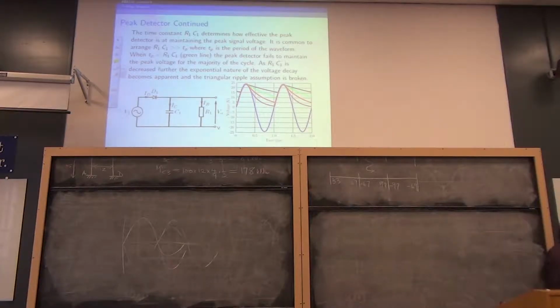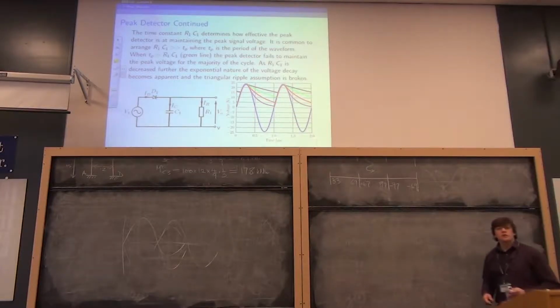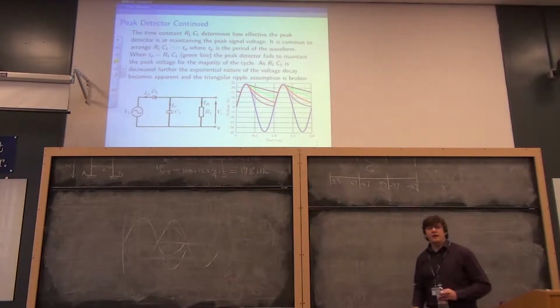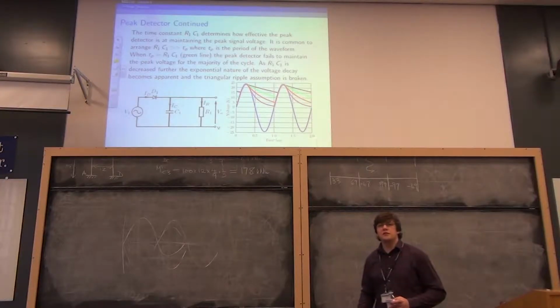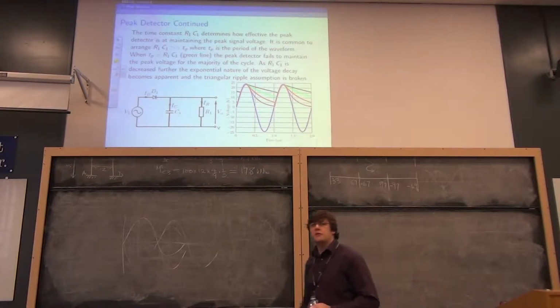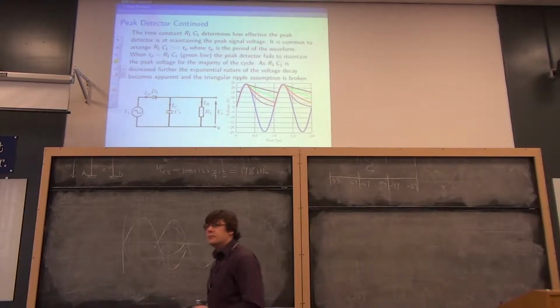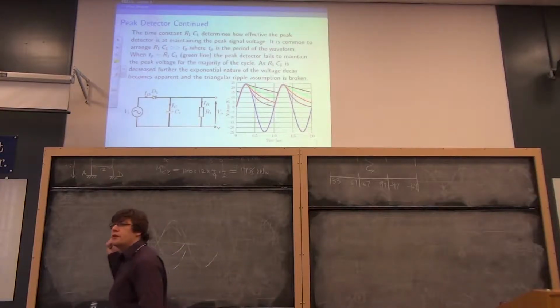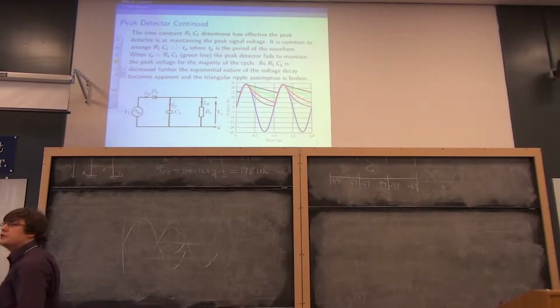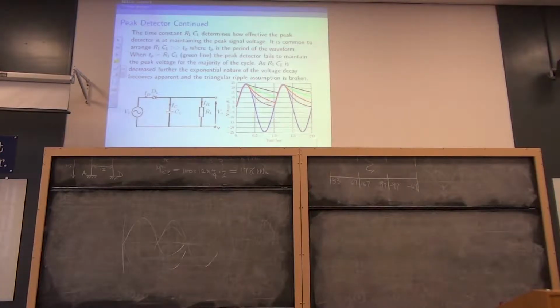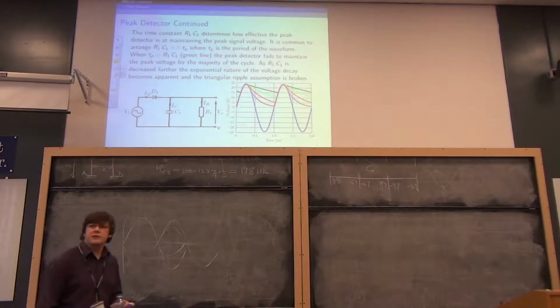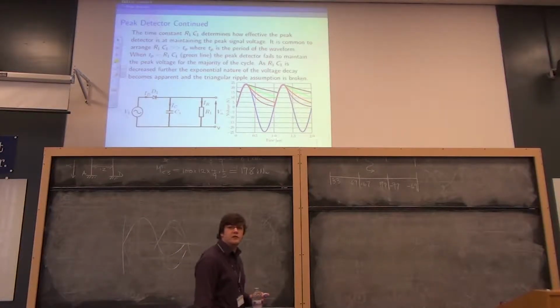So we've got to make sure, I mean the idea of this circuit is to make a DC voltage from an AC voltage. And under normal situations, especially for power supplies, we'd like the black line to be totally flat, if possible. You can't achieve that, but that's the ideal. So we'd usually make R1C1 quite large, if we can. Certainly as large as we can afford to.